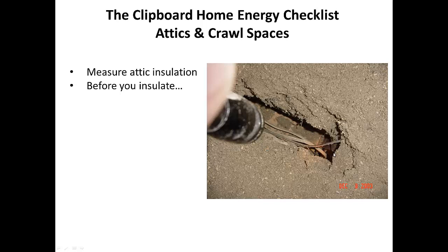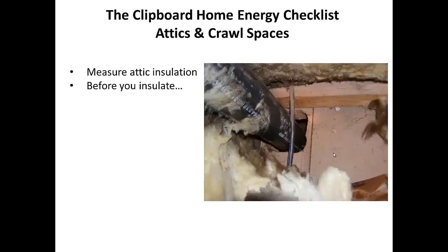These are the types of things you discover when you get into your attic and look around. You need to be very careful, because you have to walk on the ceiling joists. If you don't, you're going to put your foot right through the ceiling down below. Here's where a plumbing pipe goes through. Back when they built these houses, energy wasn't as much of a topic as it is today, so they just cut a hole and ran a pipe down there. This is probably a 4-inch vent stack pipe that goes down, and here is a great place for cold to just dive into the home.